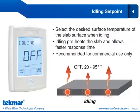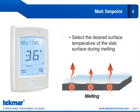So idling will preheat the slab so that you have a faster response time when it does snow. So if you keep the surface of the slab at a minimum temperature, say it's 25 degrees, when it snows, it won't take as long to bring that slab up to the melting temperature. So that's what provides you that faster response time. And because it will increase your energy usage, idling is recommended for commercial use only, typically not recommended for residential use.